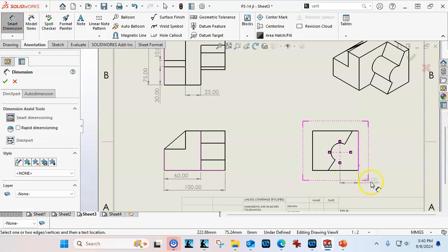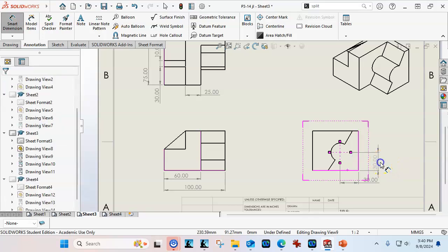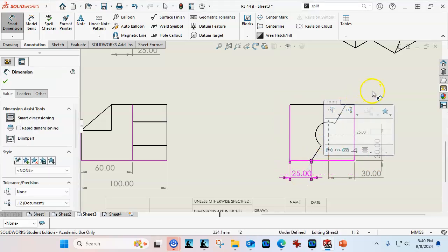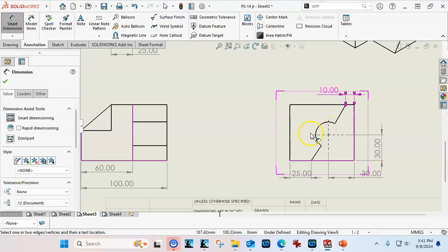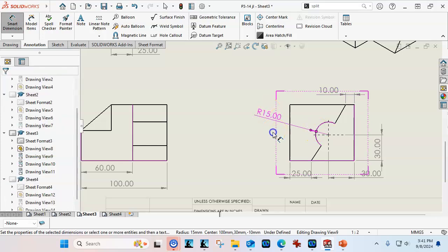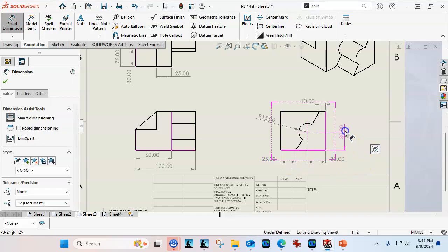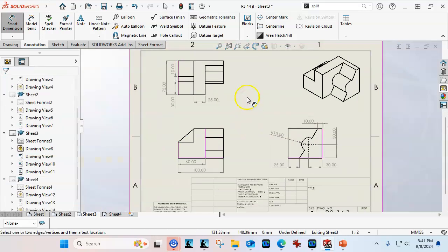So not real wild that they came off of those points to center that. I think it would have cleared it up to pick a measurable datum or a reference and place that. And then we can go from the edge to the point. And no, I don't need the modify text there. And we do need a radial dimension for 15. And we'll see what that looks like.